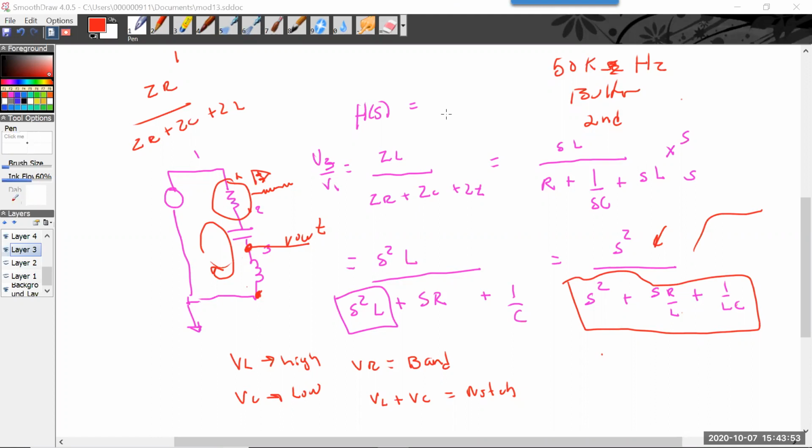What I found is that for that 5.6 millihenry inductor, for this configuration and the constraint of R min, 50 kilohertz is about as small as I can go. If I want to go below that, it won't work. I can't find an inductor that's big enough. You can find inductors that are bigger, but inductors can get big and expensive. So you always want to have more than one way to do a filter.